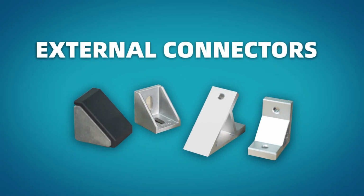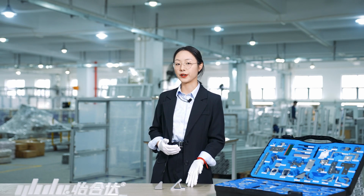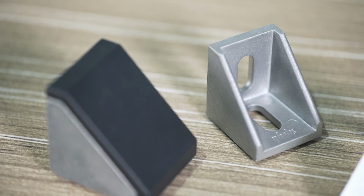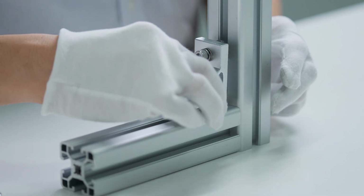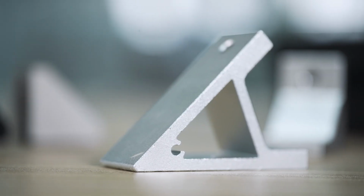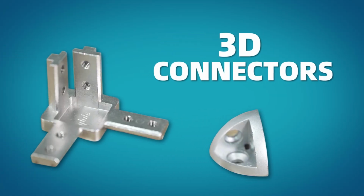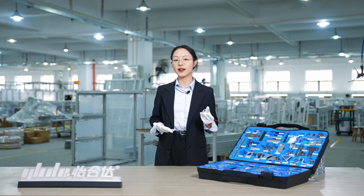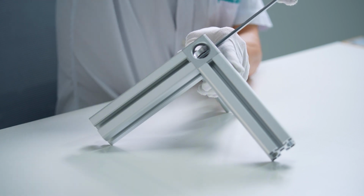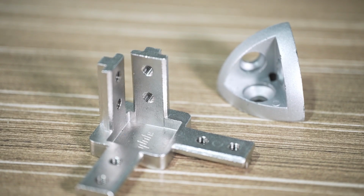External connectors. These are divided into die-cast corner bricks and extruded corner bricks, each with their own advantages and disadvantages. For standard 90-degree angle connections, we recommend die-cast corner bricks. For complex angle connections, we suggest using extruded corner bricks. 3D connectors, used to make right-angle connections between straight profiles, suitable for applications with more complex angles. You can choose between right angle or round designs.